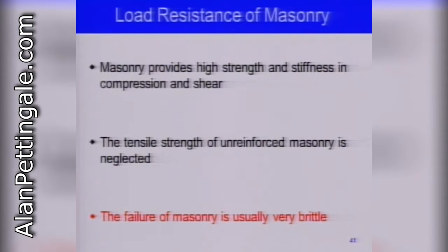What we need to take into account is that the failure of masonry is very brittle. In design terms, based on the knowledge we have from the last couple of decades, we want our structures, if they fail, to do it in a very ductile manner. That means they can deform a lot to give us a warning before they collapse. Masonry structures don't do us that favor. They don't deform that much, but suddenly they develop big cracks and then they're gone, or they can be gone. So we have to be very careful when assessing how masonry structures are doing.